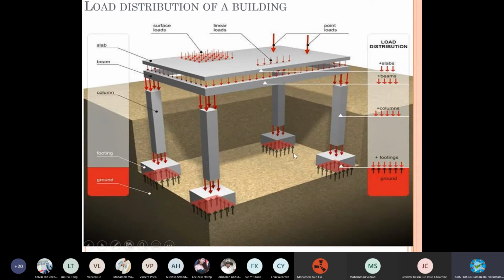Now, where we are, 3 meters. Three floors, when I say 9 meters, so up to nearly 9 meters, you don't have to bother about wind load that much. But when it is rising above 3 floors, wind load comes into the picture. You need to analyze the building for wind load before you go for construction. There are type 1, type 2, type 3, different combinations of loading. Later you will study about them when you go for design, actual designing of members, right?